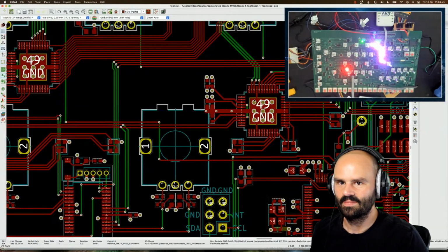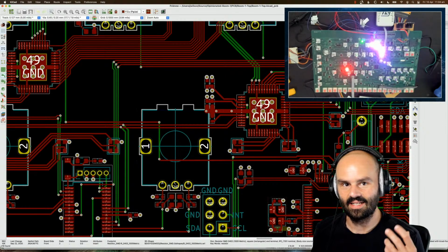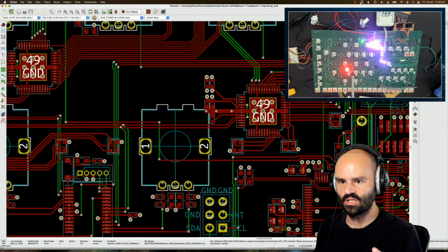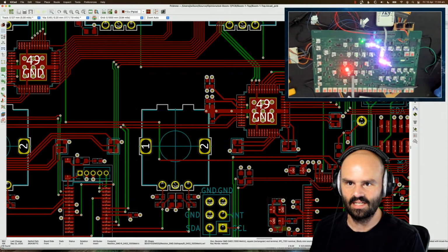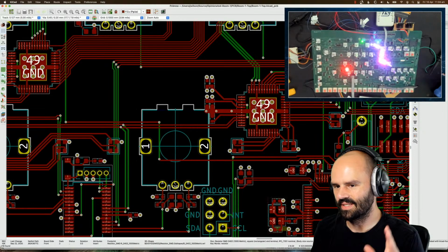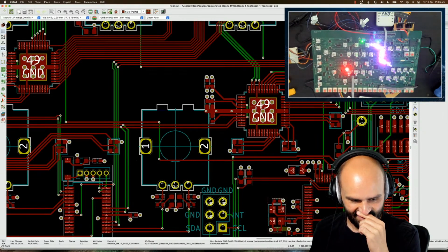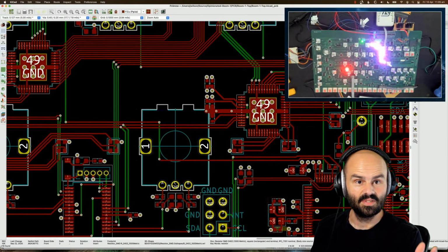We got the interrupts working for the rotary encoders. That allows that chip to then act upon the rotary encoders moving. And then we can do all sorts of fun stuff like track where it's moved, how much the value has changed. We'll be reporting that out through an I2C bus. So we've got lots and lots of code to write, which we will do together probably sometime tomorrow.